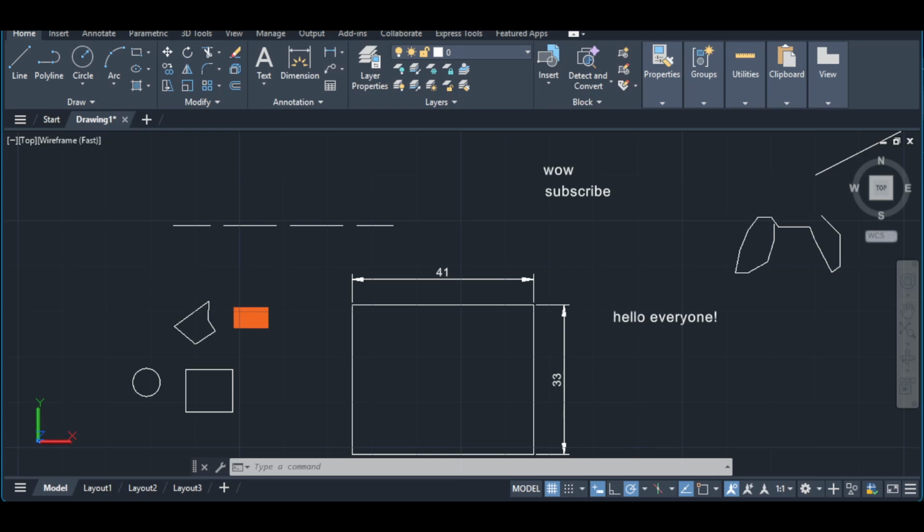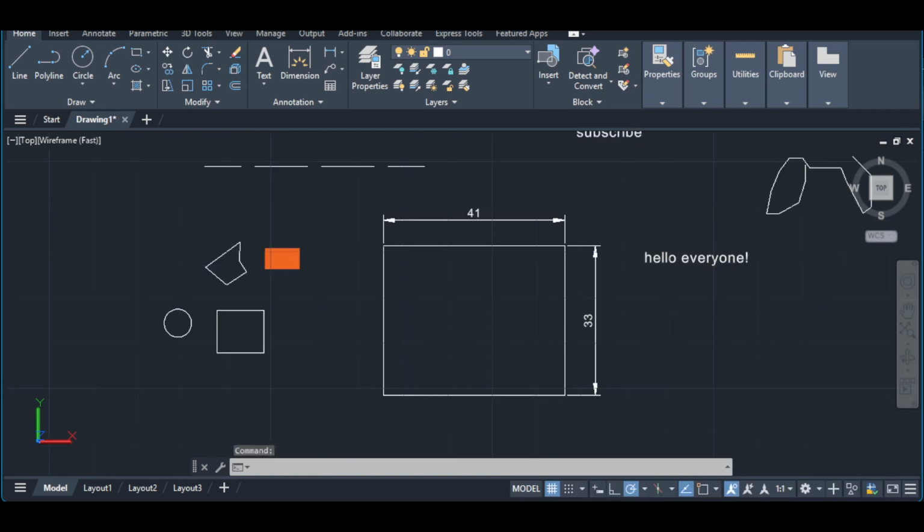In today's video, I'm going to teach you how to create and use XREFs in AutoCAD. An XREF, short for external reference, lets you reference another drawing inside your current file without permanently importing all of its geometry. This keeps your file size manageable, makes collaboration smoother, and ensures updates in the source drawing can flow through to any file that references it. Think of it as a live linked background that you can see and snap to, but don't have to duplicate.